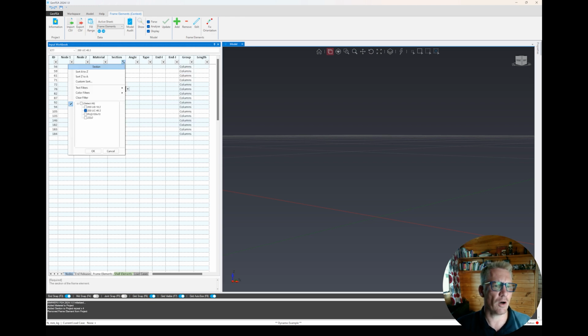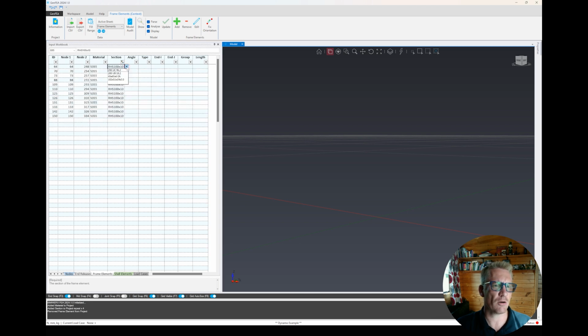And now let's move on to the angles or the bracing components. These are rectangular hollow sections that were originally specified in Advanced Steel. We're going to make them equal angles. And the group here is going to be bracing, and we'll apply the same settings here.